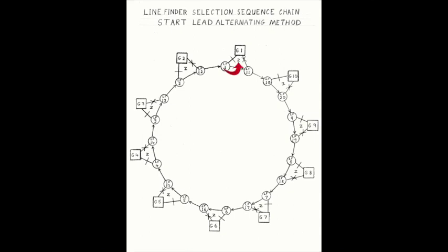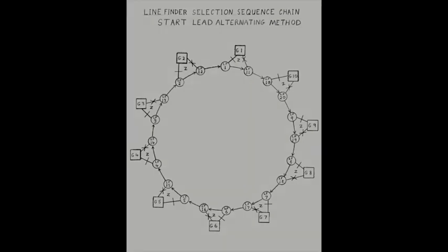The flip-flop involved a Z relay that was alternately operated on one call and released on the next. When released, a line finder on the lower shelf was first choice. When operated, a line finder on the upper shelf was first choice.